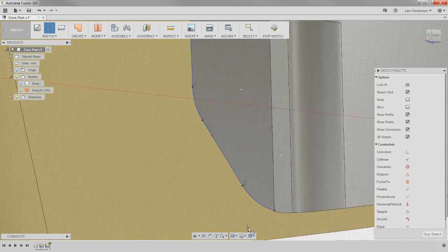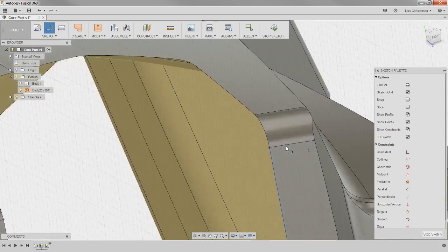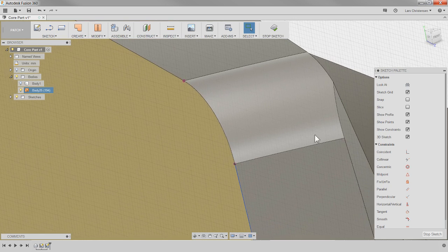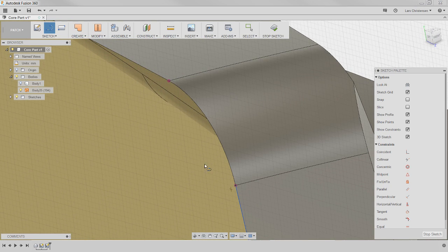Okay, that one, and then I'm going to go up and create the last portion over here. So click once for a line, go back to the center and just hold down and drag. Ooh. See how it didn't follow? See, now I'm getting a line. I don't know if you can see that. Delete that. I think sometimes you have to play around a little bit with the angle of that curve for Fusion to follow it.